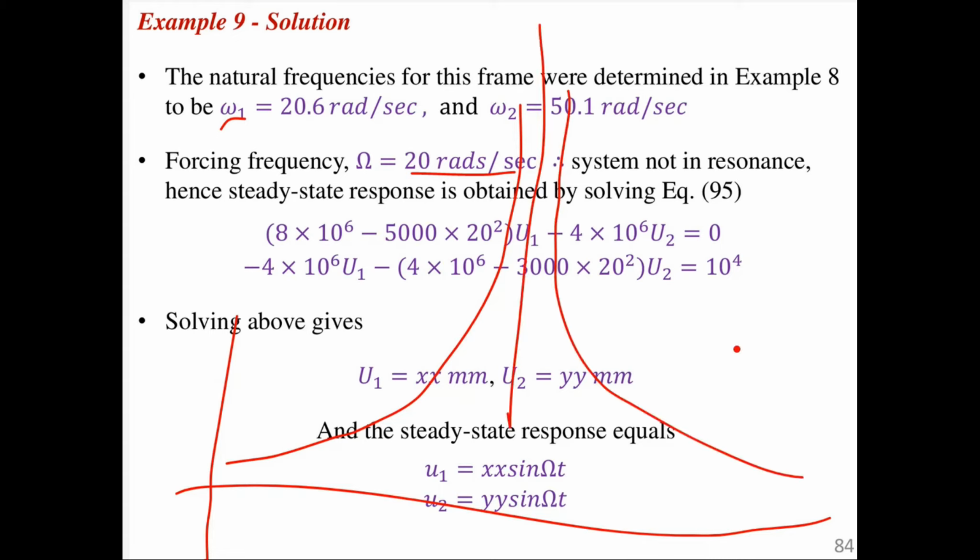That is, the frequency of the forcing function is equal to the natural frequency of the structure, and a very high amplitude is experienced. Whenever you have infinity, it means we cannot get the magnitude, so you can't get a solution. So in cases where the frequency of the forcing function is equal to any one of the natural frequencies, it may be the fundamental, or a higher harmonic, omega 2, omega 3, if you are talking of a three degree of freedom system, that is 3 stories. Then at one point our structure will have very large amplitude, and of course our structure will collapse.